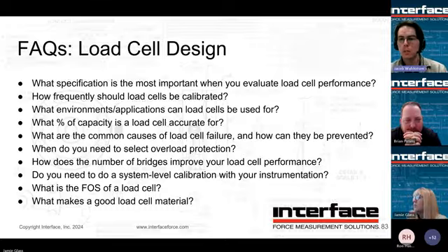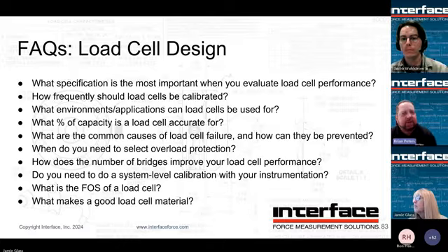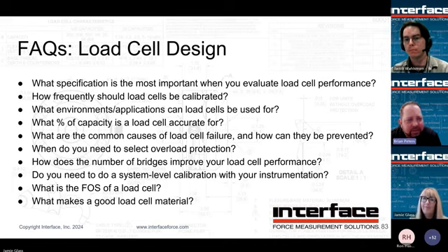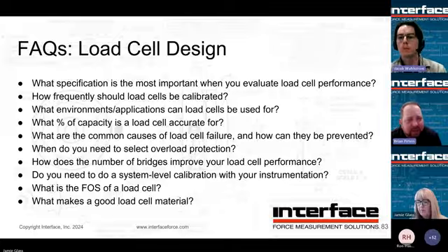Load cells are not really made to withstand shock loads, so it's really good to make sure that you're doing everything you can to avoid those. Yeah, or if they have side loads that aren't expected, right? Now all of a sudden the strain the bridge is seeing at full scale is a lot worse than maybe expected. So especially if it's high cycles, you've got to be extra careful there. Fatigue type testing. Absolutely.